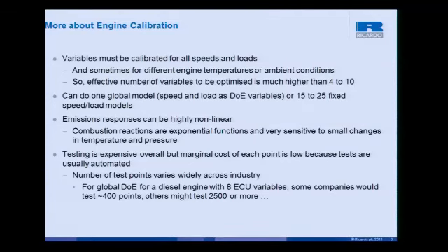Another point, testing is expensive overall, so it's maybe £10,000 a week to do engine testing, and you may have to do between 6 and 20 weeks of testing on a particular project. But because most testing is automated and runs through the night, if you like, the marginal cost of each extra test point is quite small. So changes in methods that reduce the amount of testing significantly are important, though improvements in the design that maybe save 5% of your test points is not so useful.